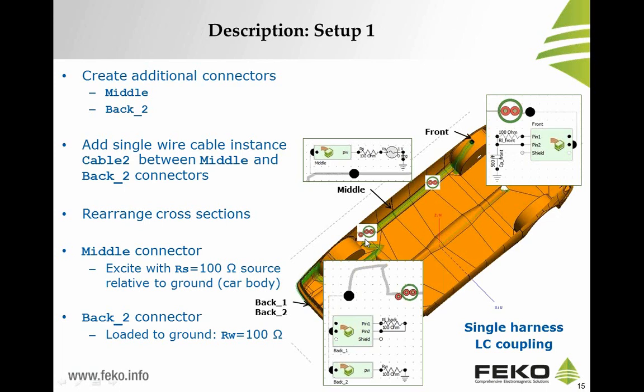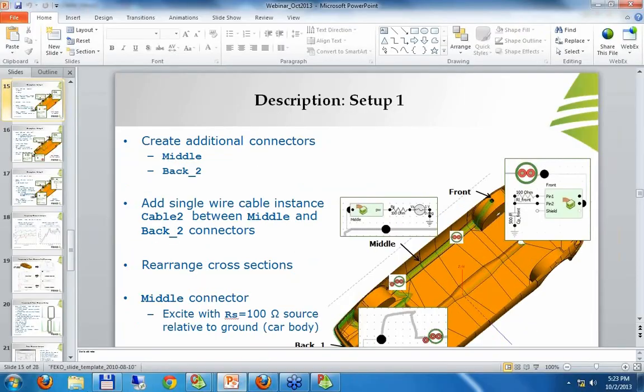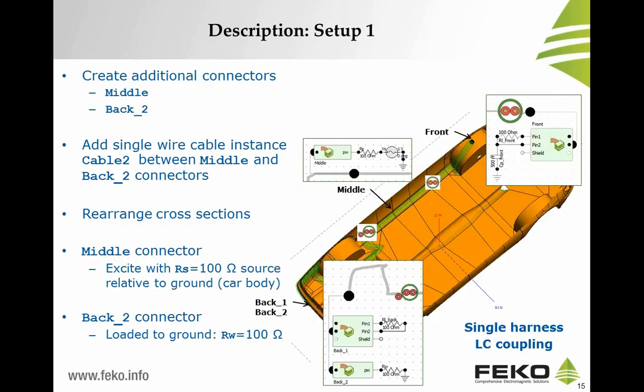Because it is so close to that, we included it in the same cable harness, in the same cable cross section, which means that we will have LC coupling between those different wires in that cable path. If we, sorry, let's just go back there.